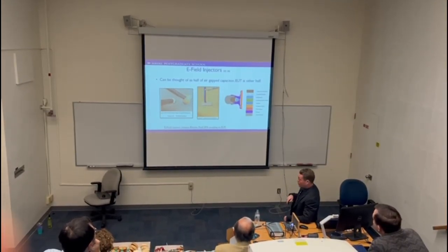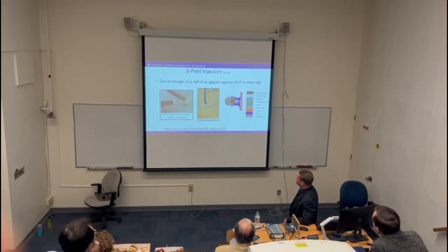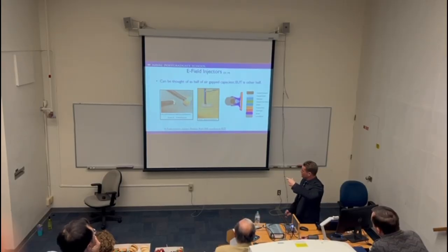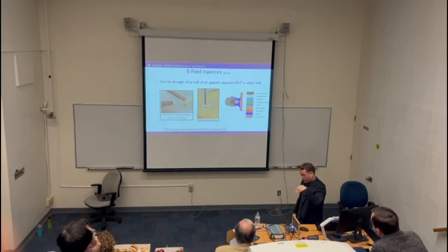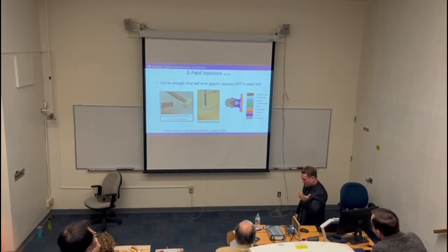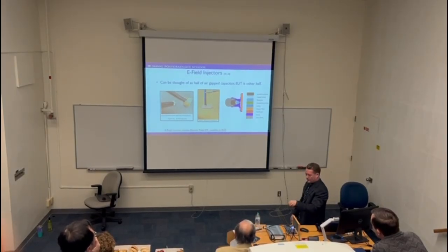E-field injectors. So this is the other side of the coin. Like I said, it's more for the common mode type coupling. You can think of this, it's pretty interesting, as half of an air gapped capacitor. I have a plate that I'm basically sending charge to, pulling charge away, sending charge to, pulling charge away, as in my sinusoidal wave.